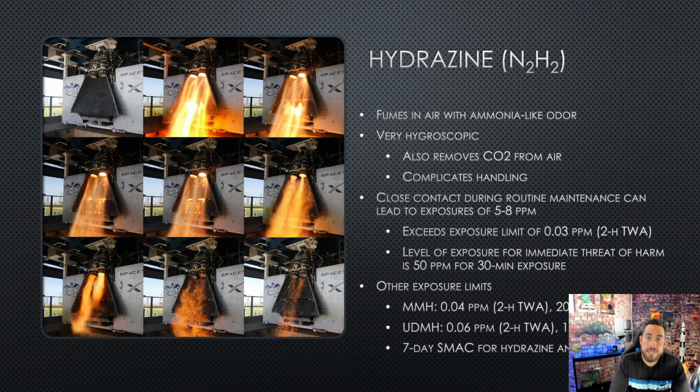All right, hydrazine, it fumes. It creates fumes in the air and gives off an ammonia-like odor. The problem is that you can't rely on smell alone to let you know if you've been exposed to hydrazine fumes. The issue is that the body can't physically detect the odor until you've already been exposed to 20 times the permissible amount. So basically by the time that you smell it, you have to go to the doctor. You have to, or go to the hospital.